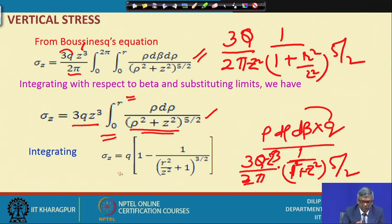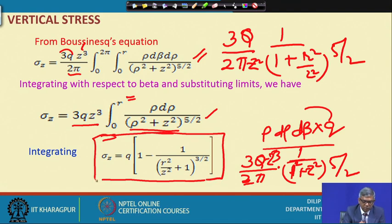If I put that, then finally I get an expression like this: sigma z equals q into, where q is the intensity of the footing applied at the surface. This is the surface footing intensity q, and at any depth it is q times this. So that means 1 minus this; as we go deeper and deeper, the stress will obviously be less, and through this equation we can get that.